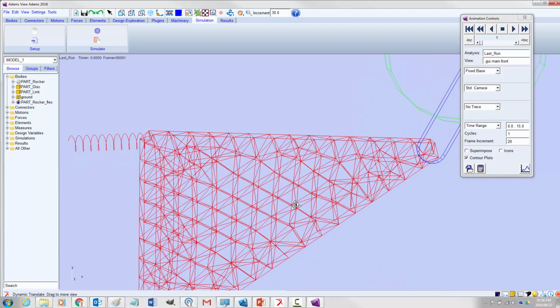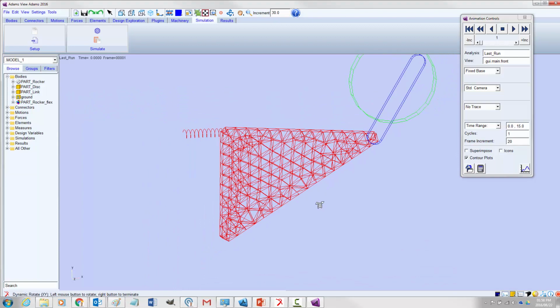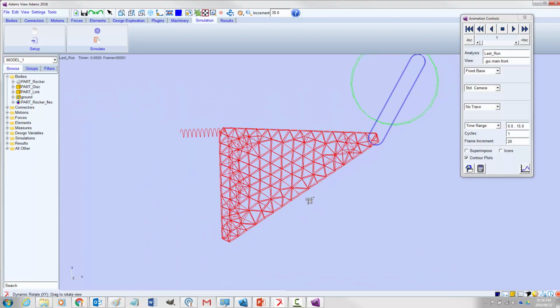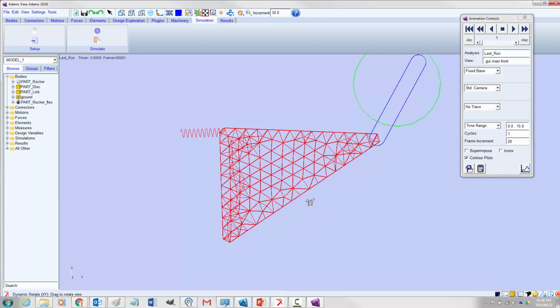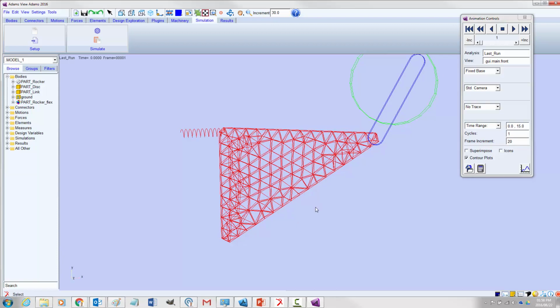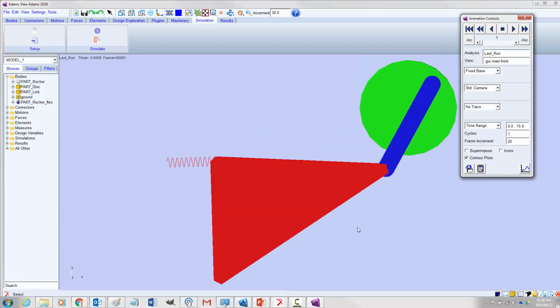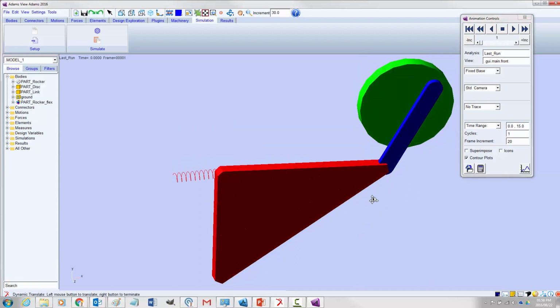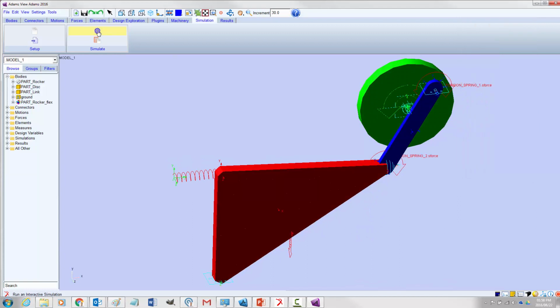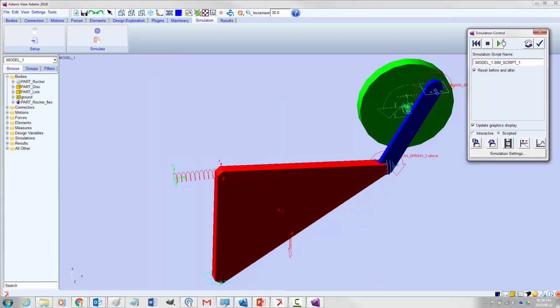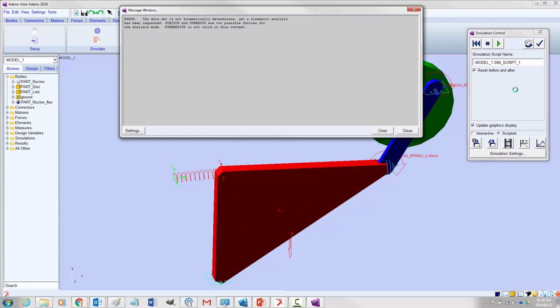Now as I said, this mesh is quite coarse and it might not be ideal for highly accurate stress values, but it's perfect for my purpose at this stage, for simply generating more accurate loads for exporting for design optimization. So now I can run the analysis, and I have created a little script that runs my analysis, and you might get this error. Now this is very important.